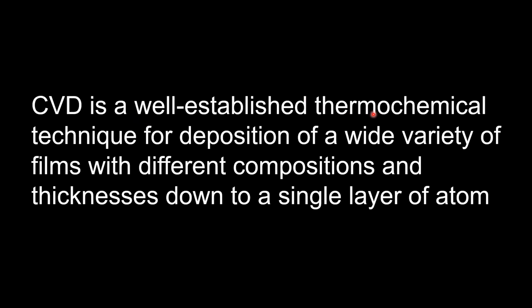What does thermochemical mean? Thermochemical means that in a CVD process, a precursor material is introduced on the surface of a substrate, and due to heat, the precursor materials will chemically react with each other, and at the end, the film will be deposited on the surface of the substrate in a solid form.